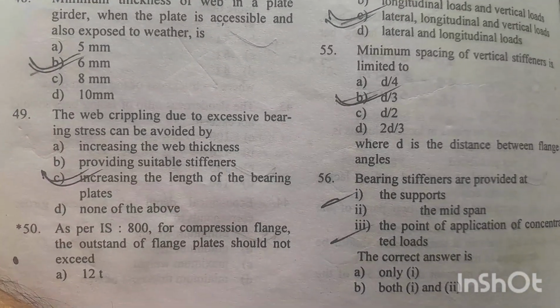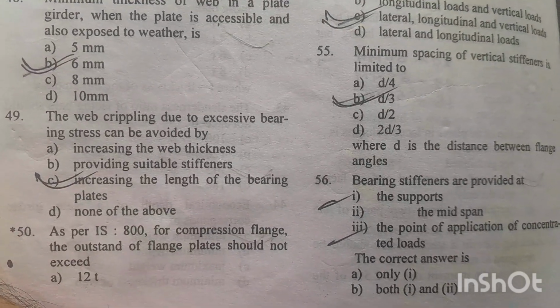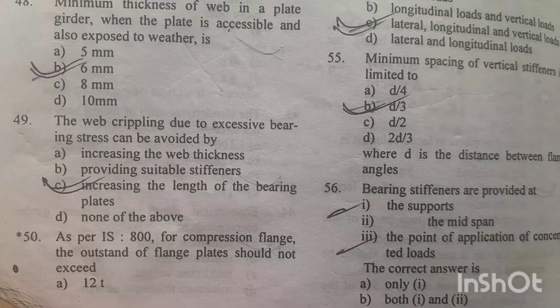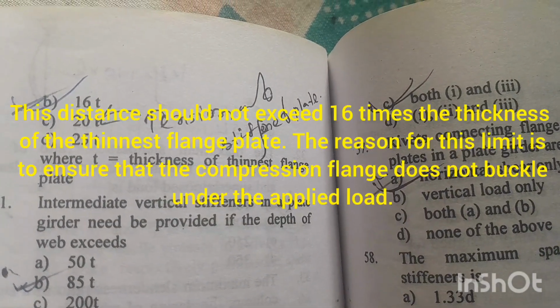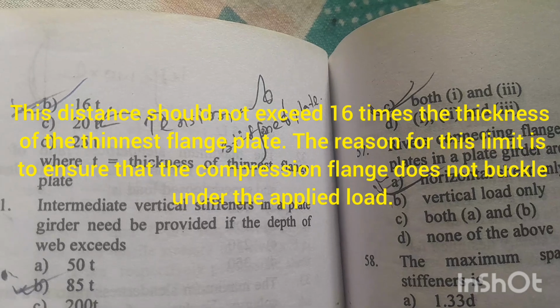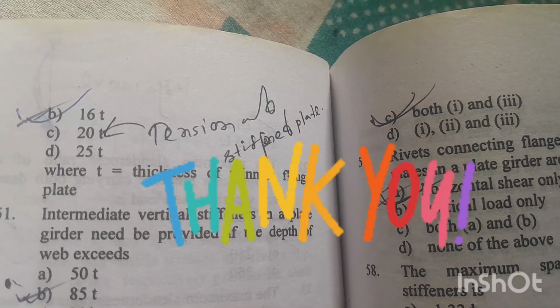Question number 50. As per IS 800, for compression flange, the outstand of flange plate should not exceed 16 T. Option B is right answer in case of compression flange, and 20 T in case of tension flange, where T is the thickness of the thinnest flange plate.